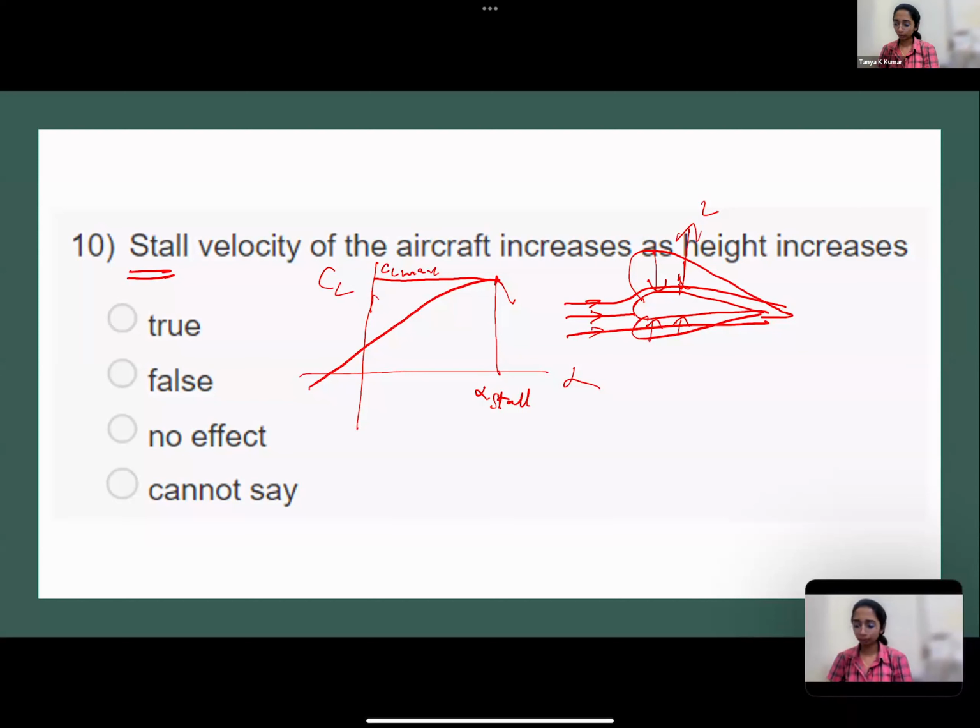Think about it. I think I had shown you this, increasing angle of attack, change in pressure profile in the first two classes. If I increase the angle of attack of the same airfoil, the pressure profile becomes something like this, right? Your upward curve is shifted ahead, your CP moves ahead.